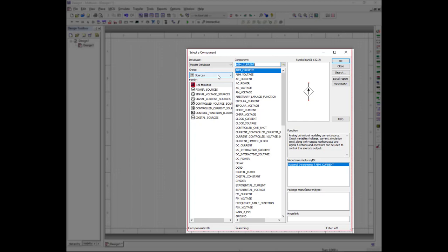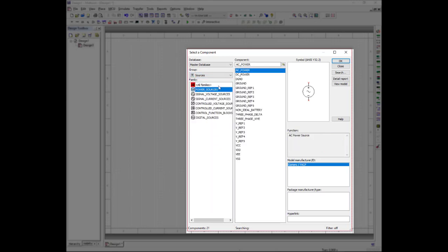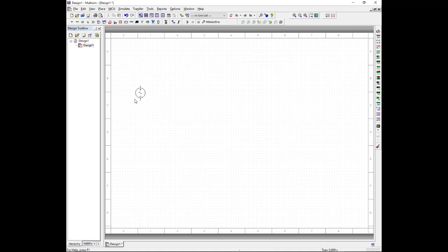And in here on the component window, under the group here, I can actually go in here and select each of those icons that was in the toolbox anyway. Okay. So I have sources, the basics, my CMOS, TTL, my power. Okay. So we're going to go with the source, power sources, and we're going to put an AC power source in here. All right. It gives us some information around the power source here, but once we have it selected in the component window, click OK, and that allows us to drop it onto our work area here.